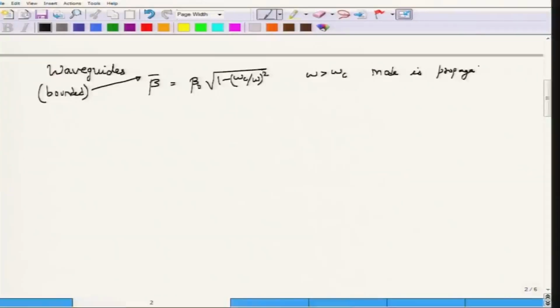So, this would be the equation for beta bar, and if you were to sketch this one on a beta bar axis versus omega axis, you would see that as long as omega is less than omega c, the corresponding beta bar will actually be equal to 0. Since omega is increasing horizontally this way, I will consider this as the cutoff frequency omega c. Until this omega c, the value of beta will be equal to 0. Thereafter, it increases in this manner.